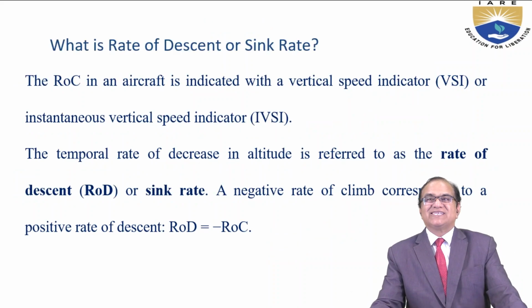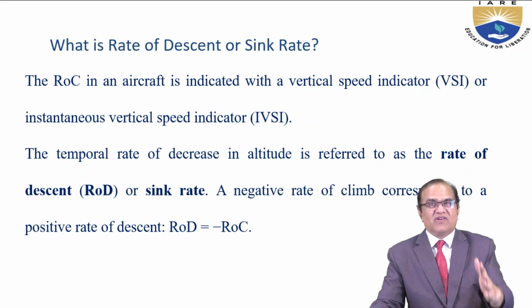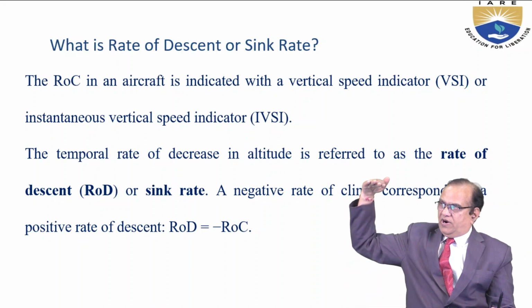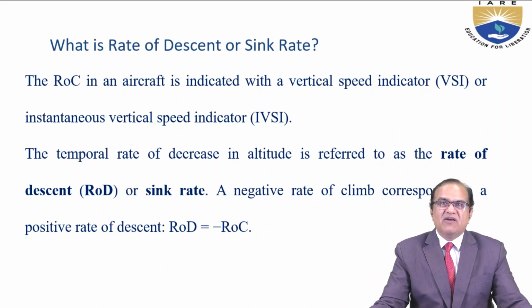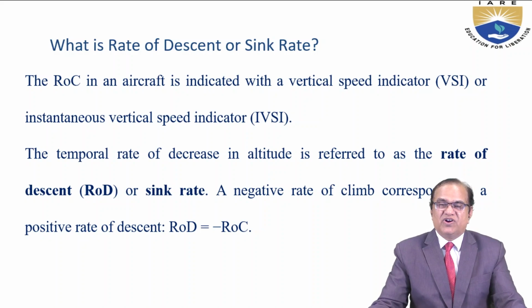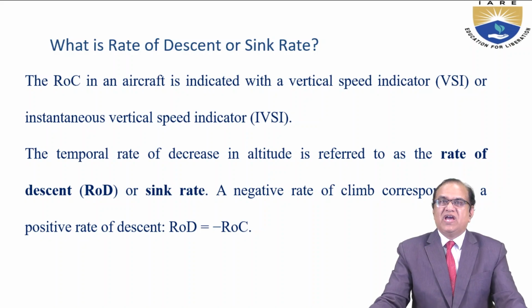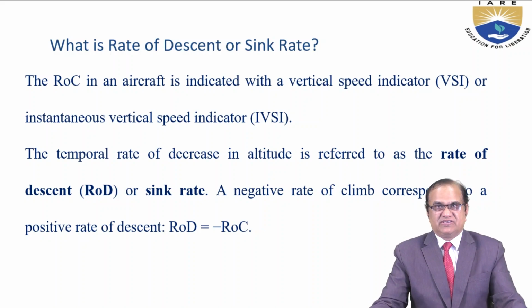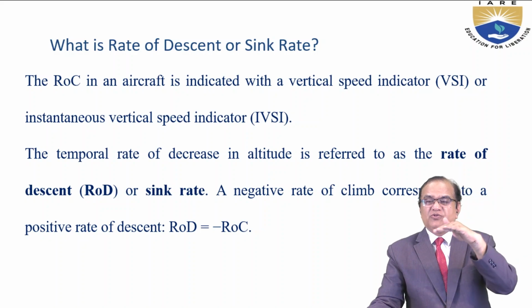What is rate of descent or the sink rate? As of now, for the climbing, it is a rate of climb. But if it is falling down from high altitude to low altitude, this is called the sink rate. The rate of climb in an aircraft is indicated with a vertical speed indicator, that is VSI, or instantaneous vertical speed indicator, that is IVSI. The temporal rate of decrease in altitude is referred to as the rate of descent or the sink rate. So how much altitude it is decreasing per unit time.